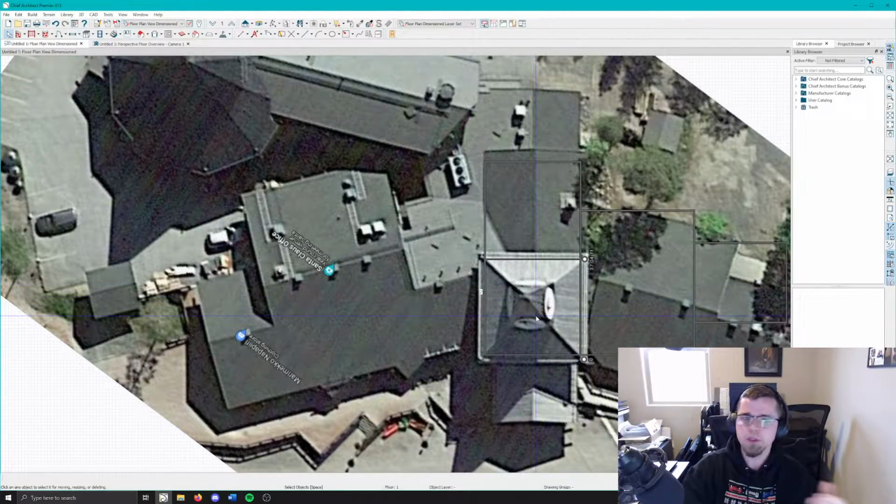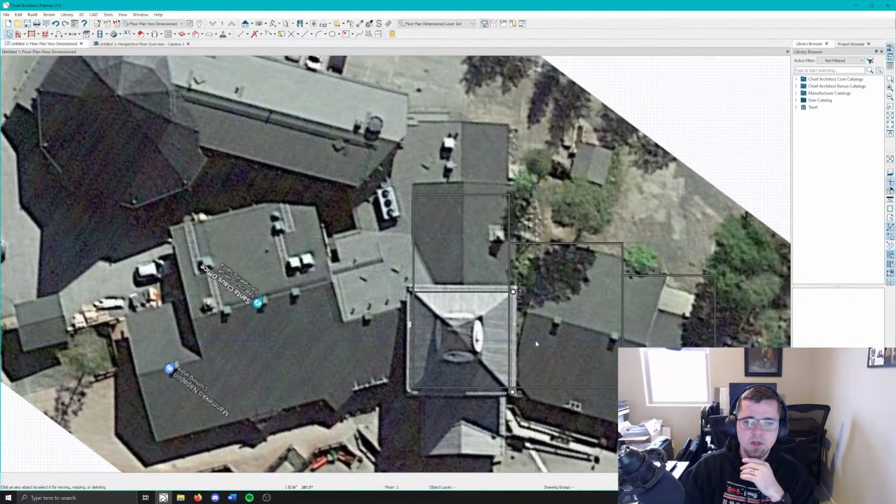If it's 6 inches, same thing. You could easily lose a few feet of space if you're just sketching on graph paper because you weren't taking into account those wall thicknesses. So we often have to go in and tweak things further to make sure you still have enough room in that bathroom. You want it to be a small 5 by 8. Now all of a sudden it's a 4 by 8, right? So we make it a little bigger.